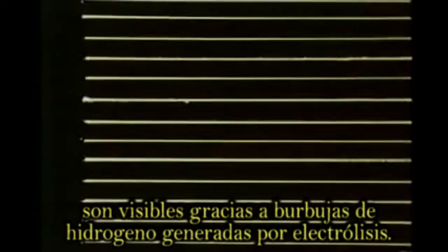These streamlines of water flowing in a channel are made visible with hydrogen bubbles generated by electrolysis. The flow is uniform and laminar. The fact that the timelines, the vertical patches of bubbles, remain perpendicular to the streamlines shows that the unobstructed flow is free of vorticity. Here is the flow over a plate. The flow is two-dimensional and laminar.